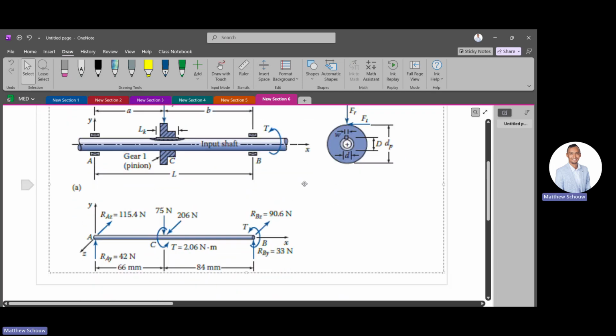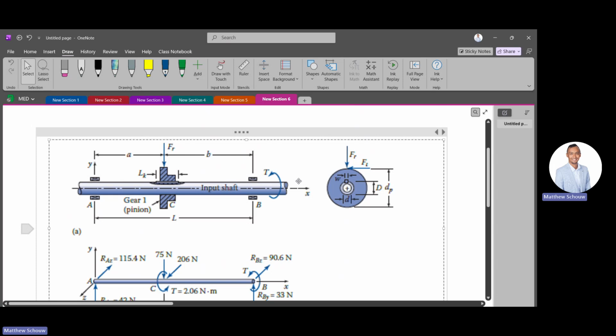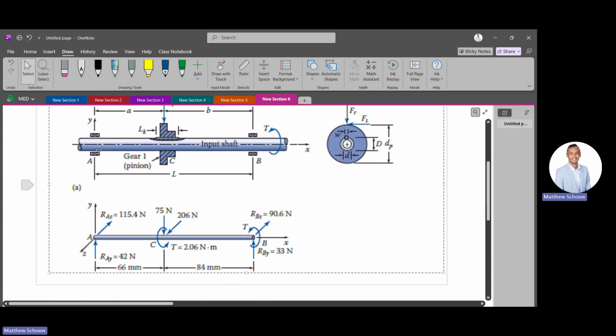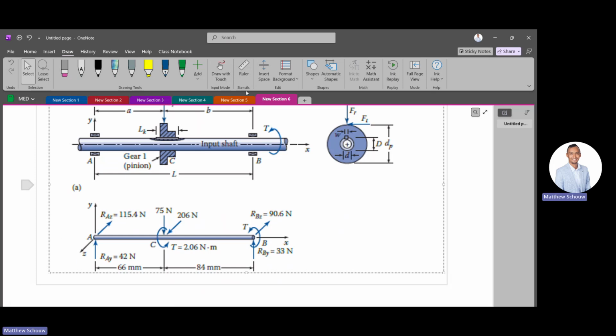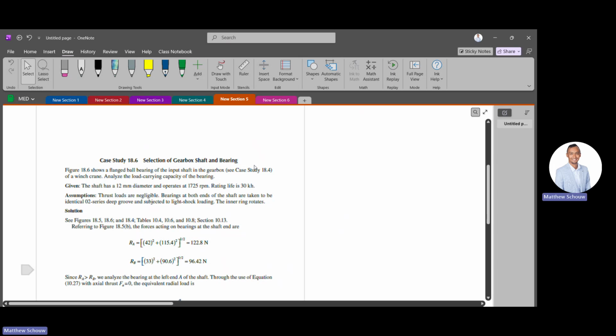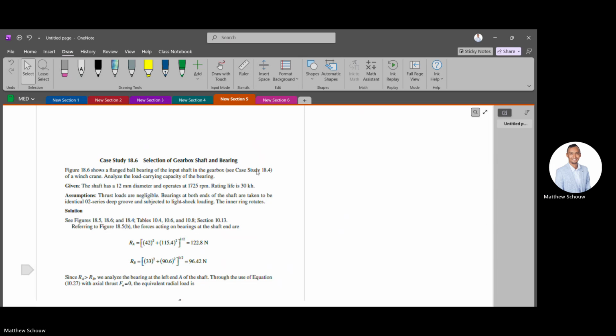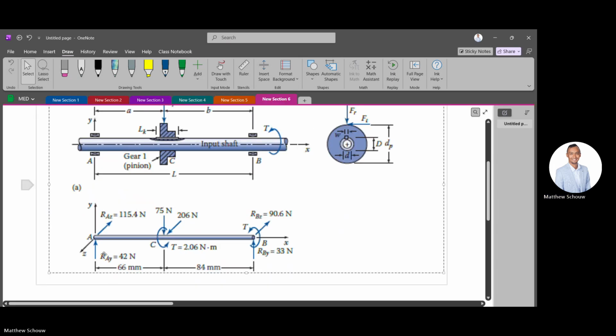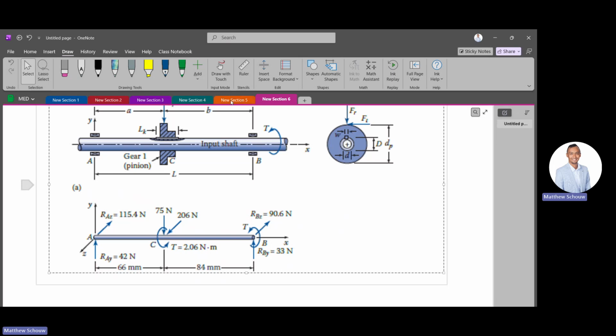Of course, it's going to assist you with the project. So it's the same standard stuff in shaft design. And we know the one bearing is there, the other bearing is there over there. And we assume that the reactions are found already. That's what's key. Based on that, we need to decide on what bearing to find. And how we're going to find it is we go to A, we find the resultant of the two reactions. That's the first step.